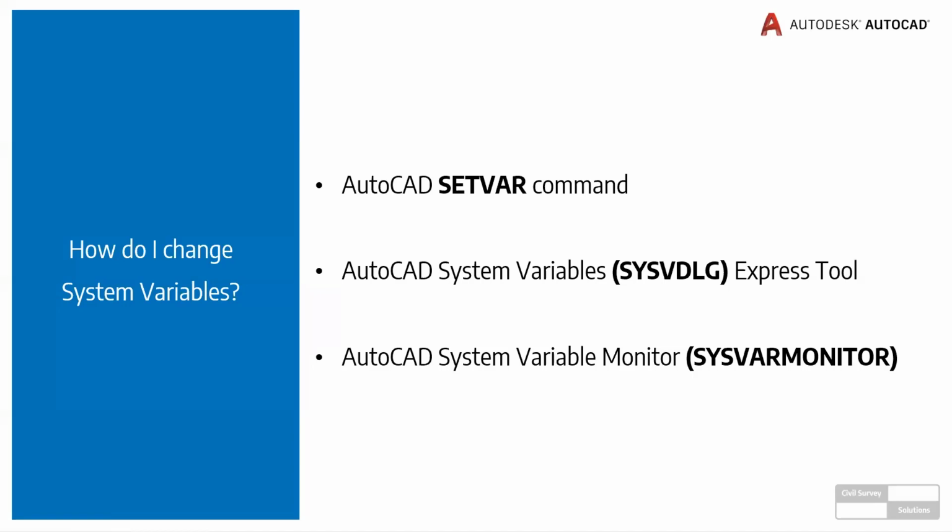You may be loading a template that doesn't have the same settings as what you're after. So you could go through and verify that the settings that are coming through on the template are the ones you want. Or you can reset them. Or with the selection modes in AutoCAD, you might have pick first set, so you can select objects. I'm not sure what changes it, but pick first is one of those variables that seems to get changed with some of the code that gets run in AutoCAD, and you would be alerted that that variable was changed.